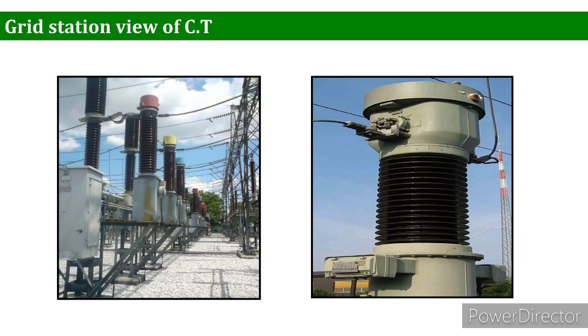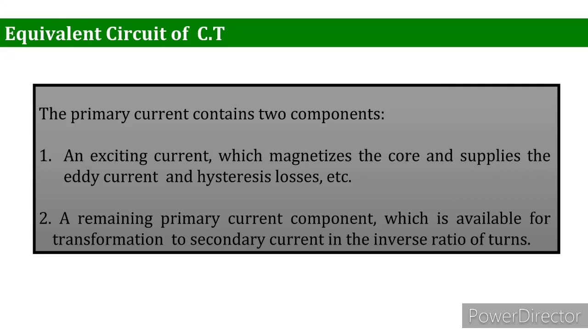The important thing is the connection. A CT has a thick bar primary connected in series between the transformer secondary and the bus bar, which can easily be judged, while the PT, potential transformer, placed on the side, has only a low current input, wire connection, and is connected in parallel.